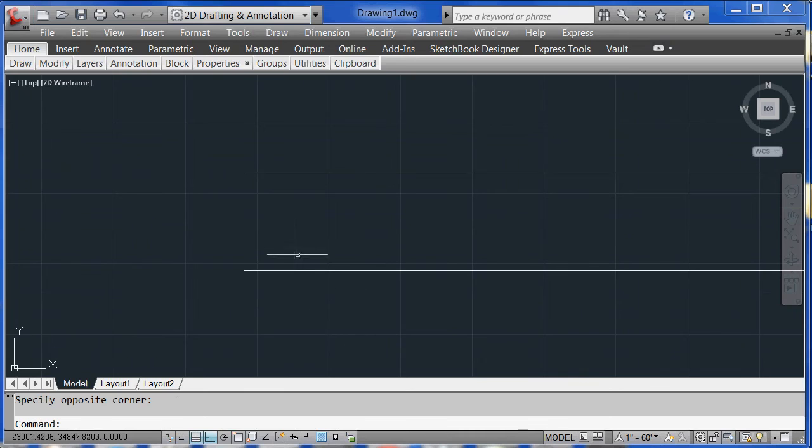The way to zoom in is you can use your middle mouse scroll button and then just zoom in or out. Or you can type the command ZW, and then you can zoom the window. But the easiest way is just using your little scroll button on the mouse. All right, so now I have this 3.5 units, and that's what figure 6 tells me my figure should be. Okay, so now I need to create a vertical line here for the one side of the wall.